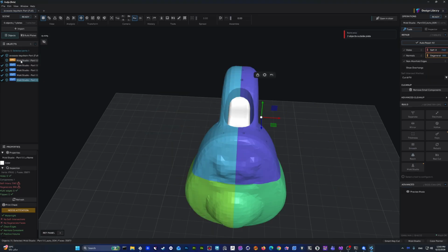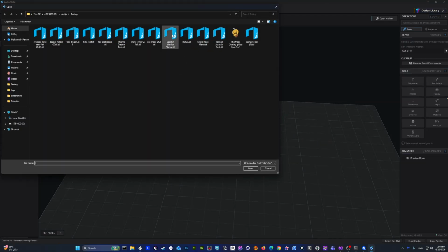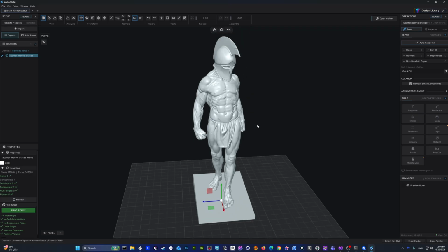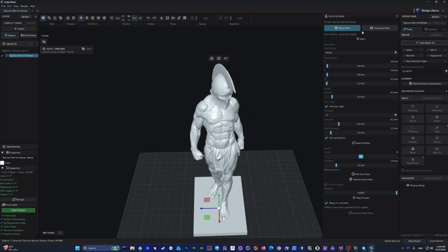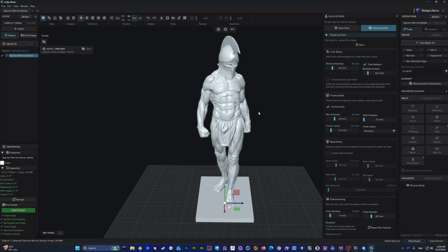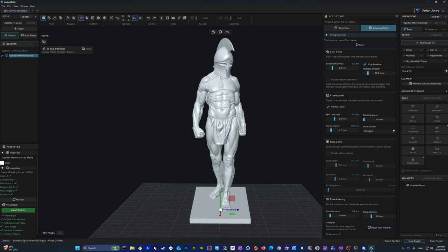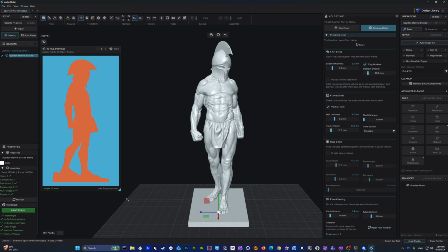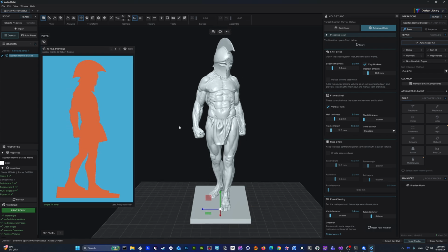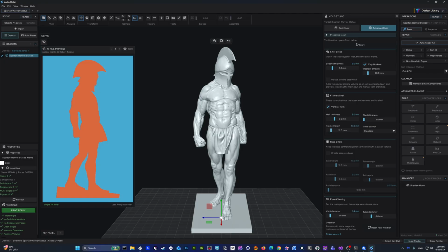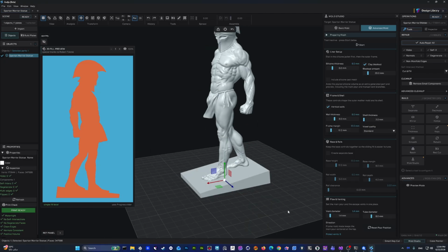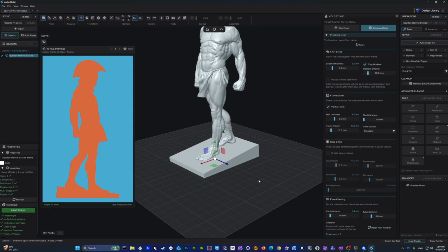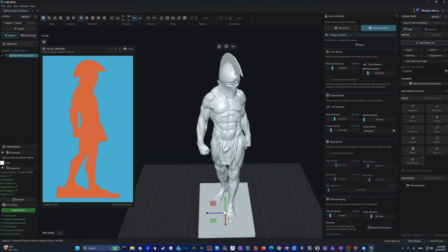Okay, so for the advanced one, I'm going to import something different. Let's say this one. If we go to Mold Studio again and move to advanced mold, first you have to know how you're going to pour your final liquid inside the silicone mold you will make. In this case we have a huge base, so we can pour the concrete from below. It will not affect any details, and we will not use the upper part.